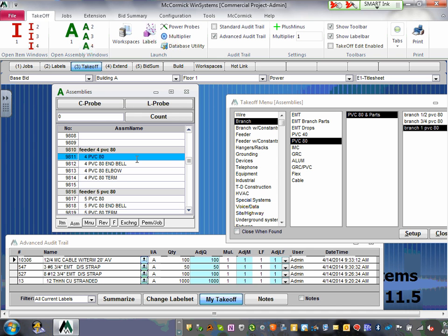Okay. For your branch circuits, Karen, you need to take branch circuits, like I said, guys, the 8 conductors, number 12 and 3/4 of an inch. That's default, and the MC 12/4. Let's go right underneath it, guys. Click onto feeder. Click on feeders. Can you guys see where feeders? What's the difference between feeders and branch circuits? Adam, the difference between feeders and branch circuits, it gives you a bigger conductor in different conduit, larger conductors.